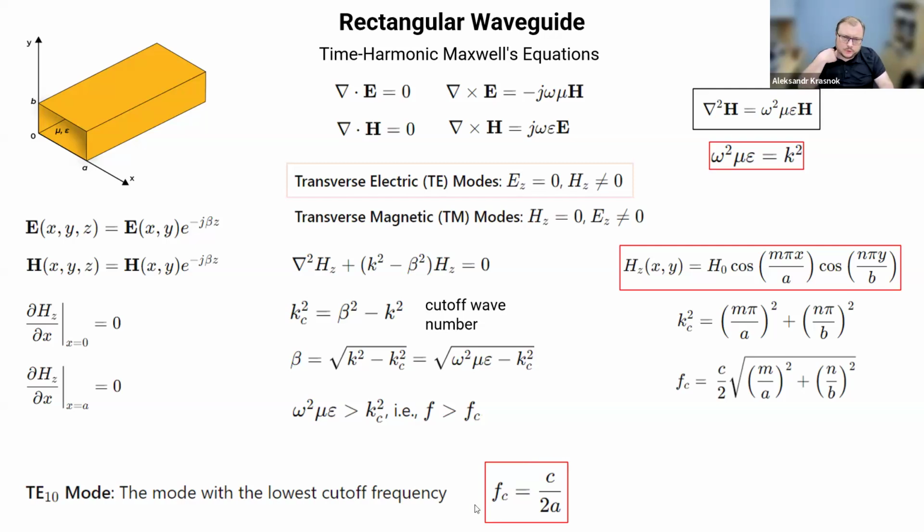In your simulation, you will be calculating the waveguide around this cutoff frequency, and you will see that below this frequency there is no propagating field, no propagating mode. The field will just be decaying in space, but just above this frequency, you will see this nicely propagating waveguiding field.